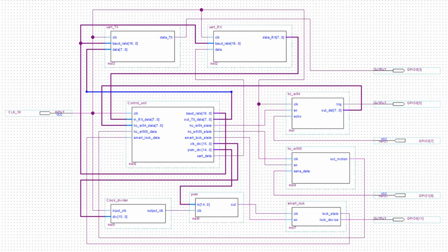The hardware part of the project consists of a server organized on the basis of a computer to which the camera is connected, DE10 Nano boards to which the smart lock is connected, HC-SR04 rangefinder sensors, a DHT11 temperature and humidity sensor, an MG90S servo drive, an SR505 motion sensor, indicator LEDs and relays.